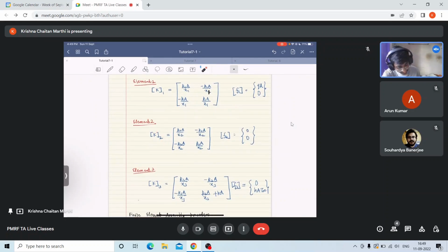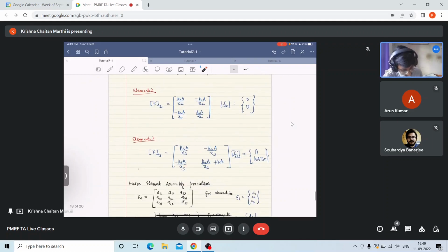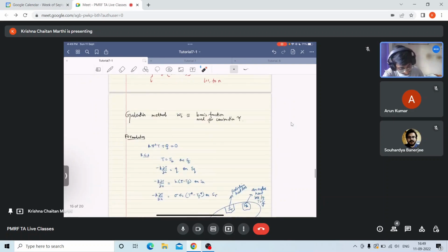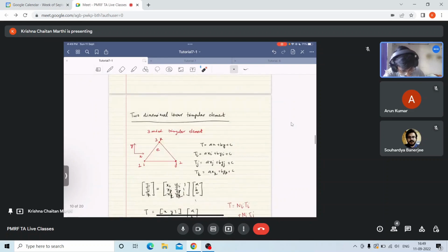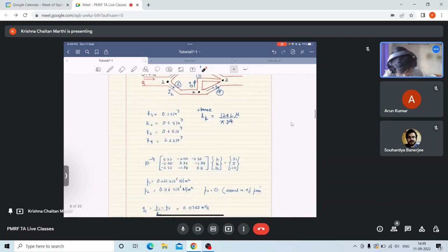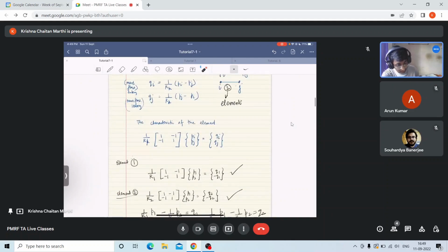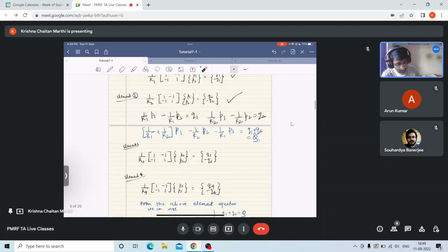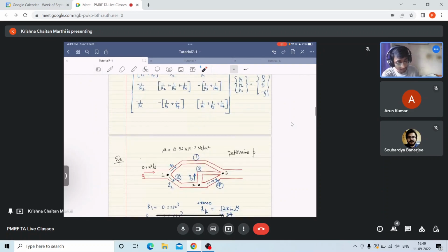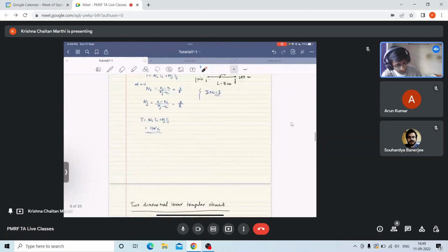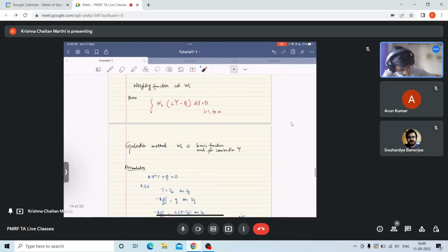Similarly, the second element can be written as this, and the third element can be written like this. Okay, so like in the fluid flow network problem, first we have written the characteristic of the element for each element, and also we have written this global matrix, right? So how to do the assembly, that we will look at now.